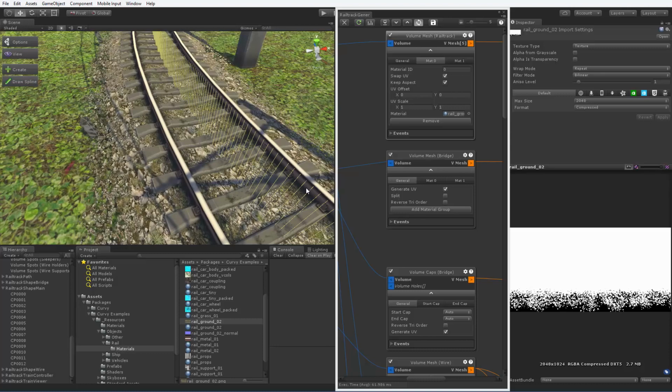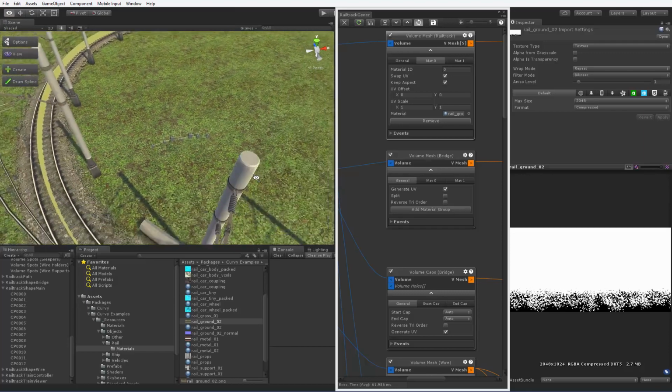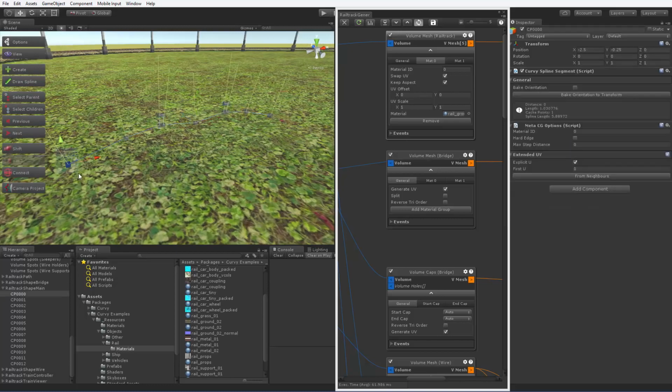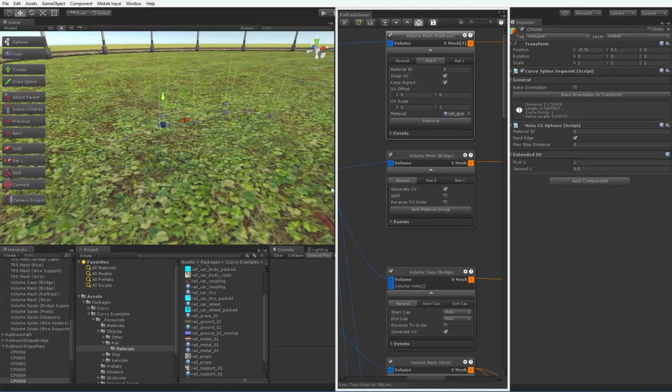You can take a look at the scene 26 later, which contains a very elaborate example of control point-based texture mapping. So, taking a look at the cross-section again. Here we have coordinate of 0 on the control point 0 and the coordinate of 0.5 on control point 2. As it's also a material edge where the rail metal starts, we have another coordinate we can input. In this case, we use 0. We then go to the control point 5 here, which again switches the material ID from 1 to 0 and input the coordinate of 1 for the rail metal here, making it proportionally stretched over the rail, like this.